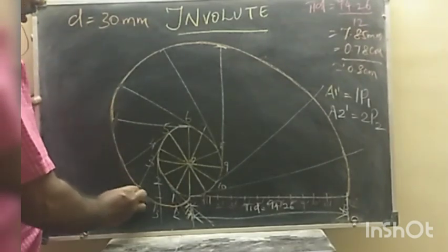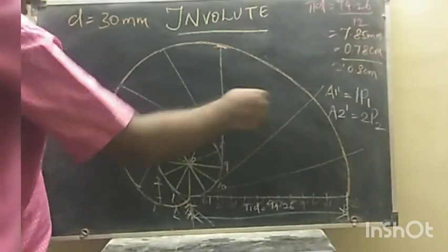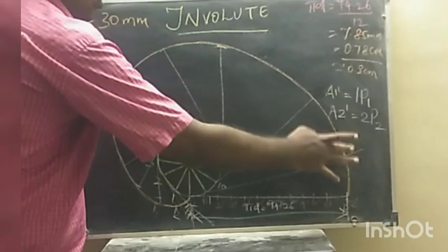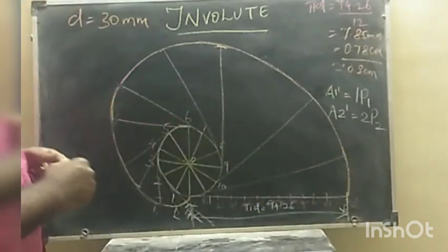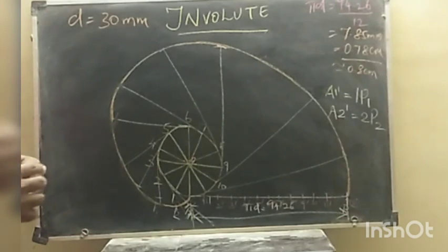to see. So please don't forget it, and whenever you are going to draw all these tangential lines, they should be very thin. You should not draw them very dark. So ensure that they are very thin. Okay, so this is the procedure for drawing an involute curve.